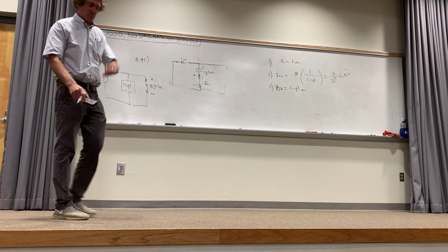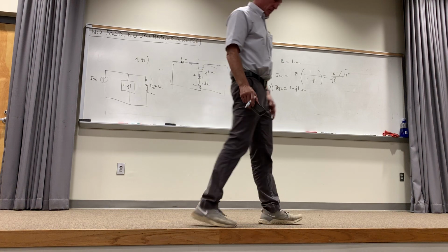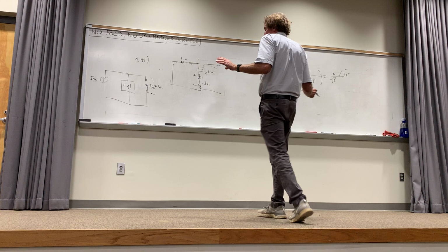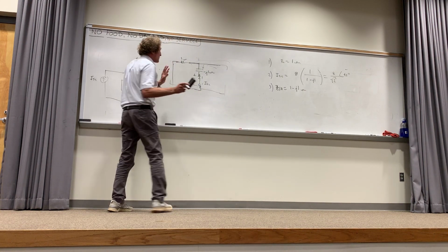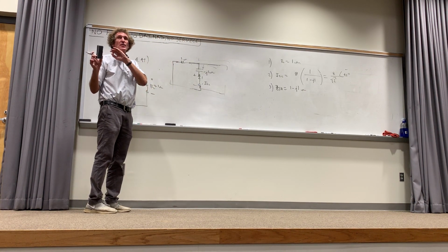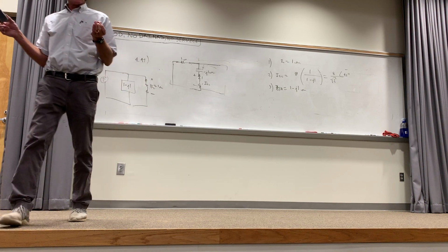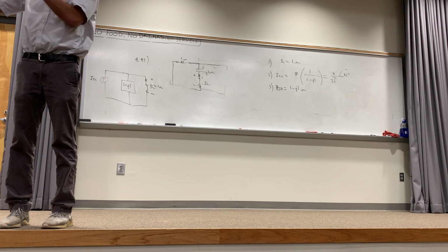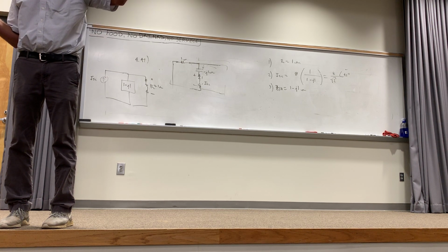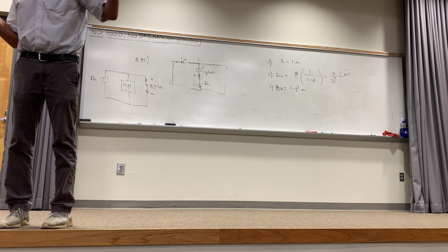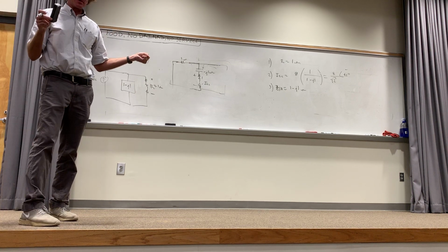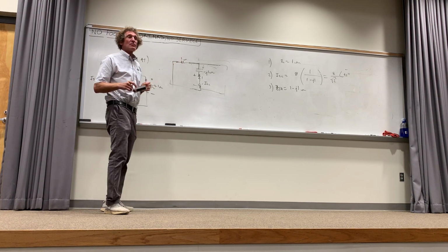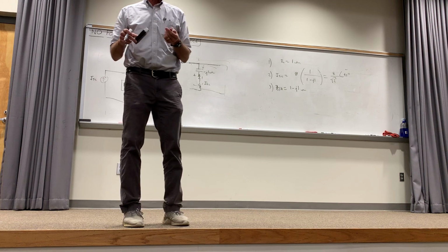If you wanted to find the voltage drop across the 1 ohm resistor on top, was there an easy way to do that from what you've already done, or do you have to do a whole other analysis? Well, first, this is an interesting point. The whole purpose of Thevenin or Norton is to eliminate the circuit itself and really boil it down to 2 components, a source and an impedance. And then any load you stick in where that load was, you can analyze quickly. So you can't go back and say, well, we can calculate this now. No, that would come from a mesh or nodal analysis, all right?